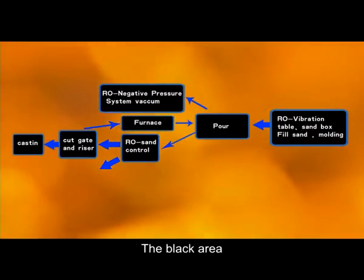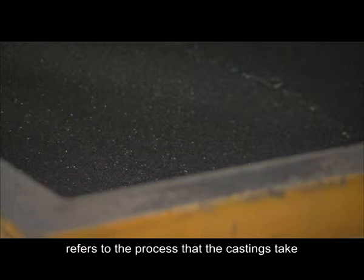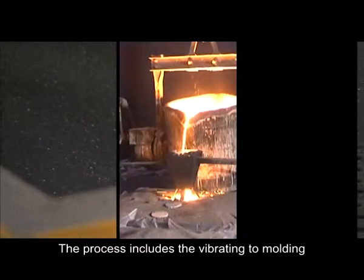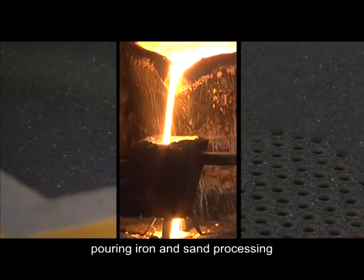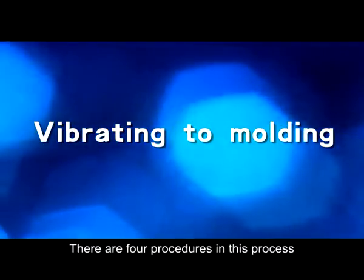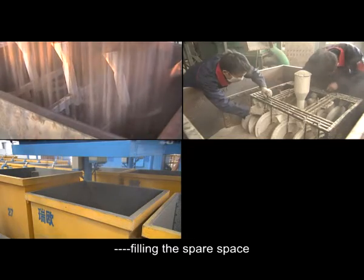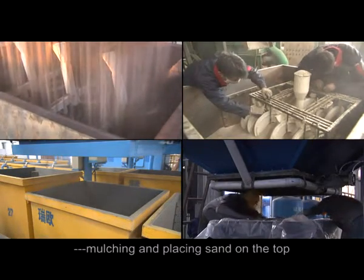The black area of the lost foam casting process refers to the process in which the castings take the place of the white pattern. The process includes vibrating molding, pouring iron, and sand processing. Vibrating molding has four procedures: bottom sand, placing EPS patterns, filling the spare space, and mounting and placing sand on the top.